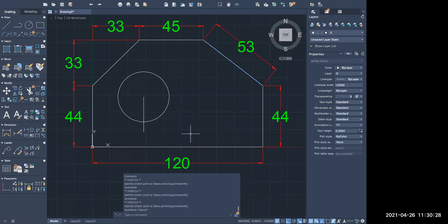Yeah. So one more tool I would like to tell you here, you can see here, object snap, on the right bottom corner. Just now I told you only about ortho mode. Now I am telling you about this object snap. What is the function of this object snap? Now I will show you with one example. I draw one line. For that, the command is L, enter. Now it is asking to specify the first point.